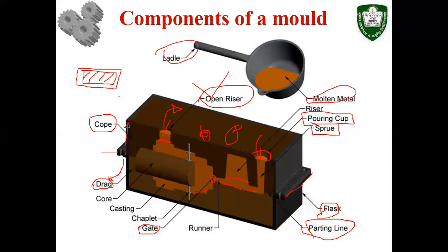Why does it happen? Because of the addition of heat, the atoms or molecules of this material get kinetic energy, and the distance between the atoms increases, and that is why the volume of the material increases, and in the case of liquid, it increases significantly.